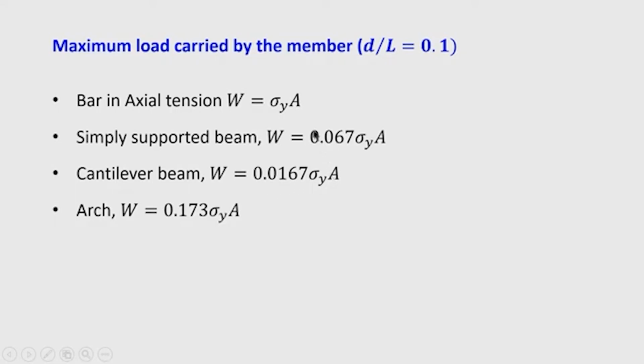So, from this simple analysis, we can see that the maximum load for the same cross section, same material and same member length or dimension can be achieved in the member which is subjected only to the extensional mode.